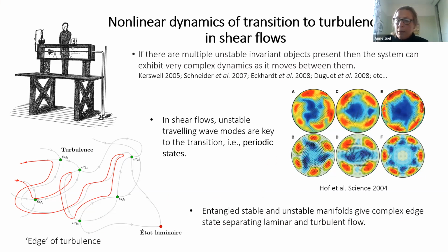So we know nowhere near the complexity of these 3D Navier-Stokes equations, and in a sense you can say that's an advantage, because we can actually carry out direct numerical simulations quite easily of our 2D depth-averaged model to look at exactly what the basic dynamics that occur in the Hele-Shaw channel are.